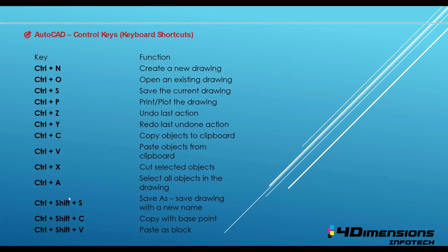The next one is Control Shift plus S to save as. Even you can directly go with Control S. Control plus Shift plus C, copy with the base point. Control plus Shift plus V, paste as a block.